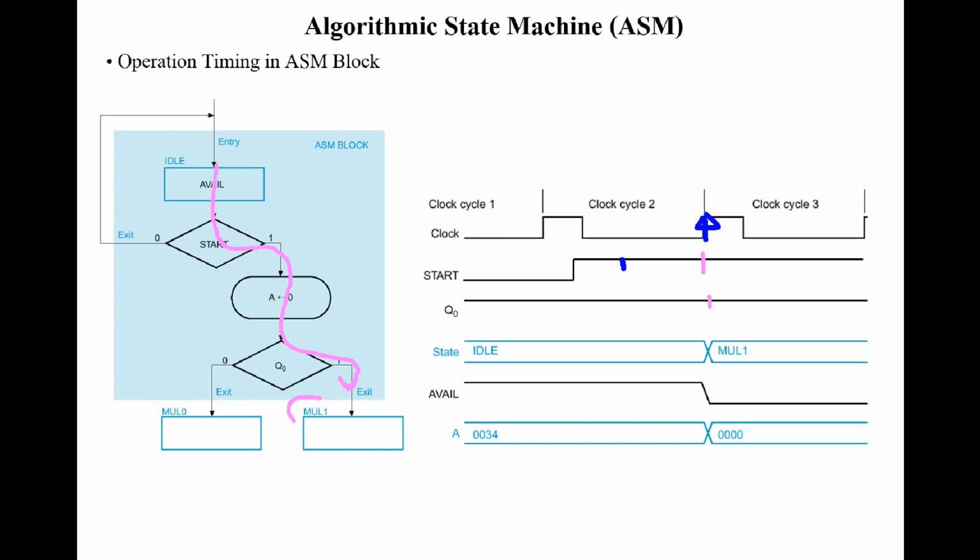So it goes to state -1, the state changes to -1, and in this state box we write nothing. That means no output is active. So output eval changes to 0. Same thing, you can write eval is 0 here, and it's 1 here.